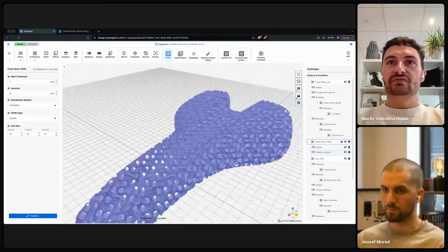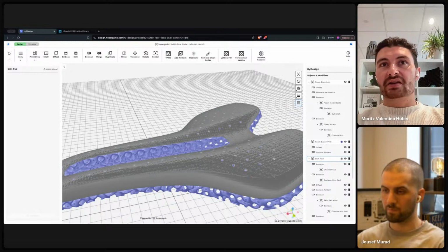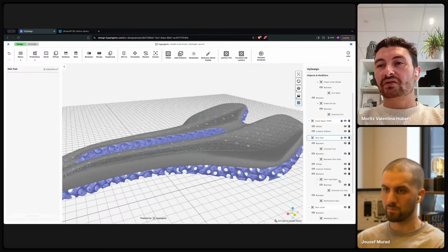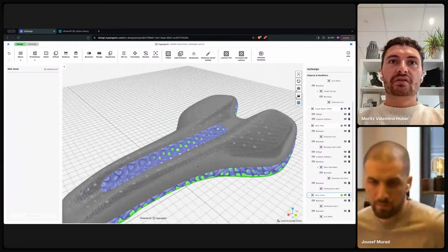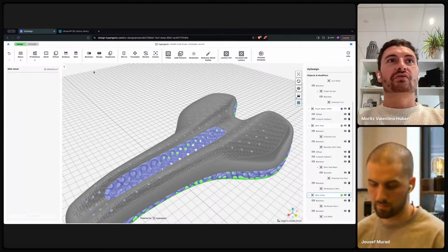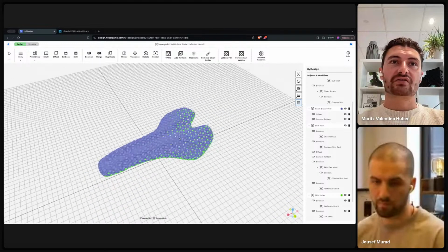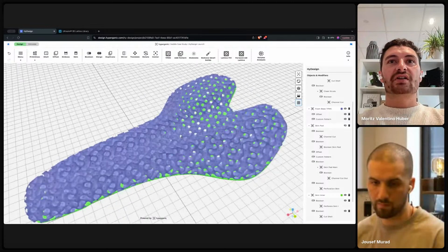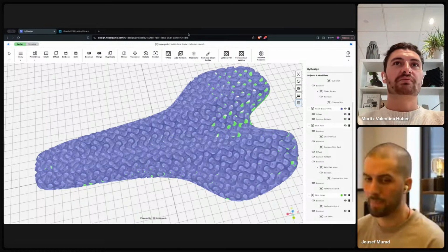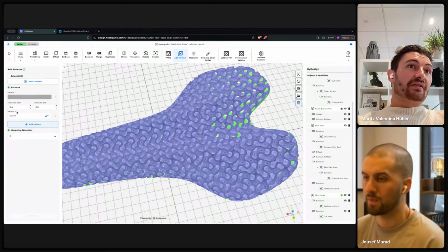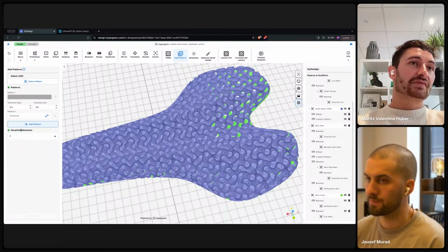So I could, for example, also use the gyroid now for the saddle, and then add the other components like the skin on the top and on the bottom here. And then, of course, I could do all sorts of other things to this gyroid. I'll quickly unview the skin pad on the top. Let's say I want this gyroid in the back, and I want another TPMS in the front. So I'll merge this, as I was showing before, into, for example, a Schwarz diamond again.